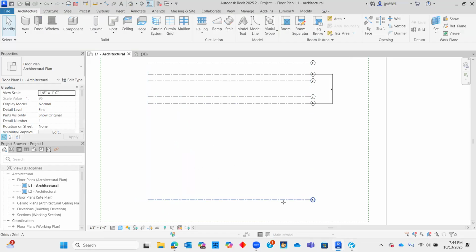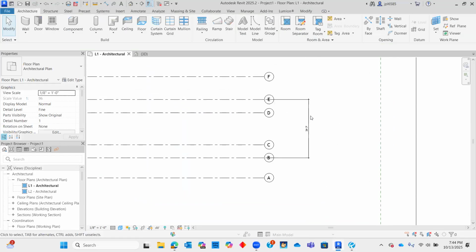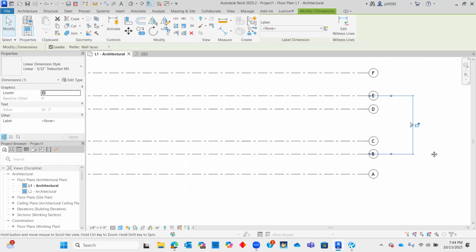So what I did is that these grid lines, sometimes when you click on them, they have dimensions already, kind of like this little phantom dimension, right? And you can adjust where it uses as its endpoints. So I adjusted it from grid line B to C. So doing that, I'm going to adjust the distance, and it should be 14.10 between them, and press enter. Perfect. So now all of these should be